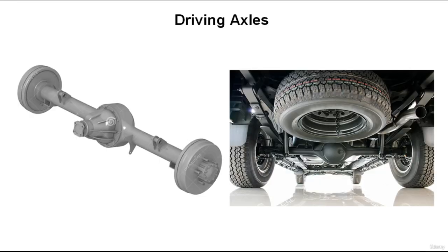Also, we have the driving axles. Driving axles are solid steel shafts that transfer the torque from the differential to the driving wheels. A separate axle shaft is used for each driving wheel in a rear-wheel drive vehicle. The driving axles are part of the differential and are enclosed in an axle housing that protects and supports these parts. Some rear drive axle units are mounted to an independent suspension, and the drive axle assembly is similar to that of a front-wheel drive vehicle.